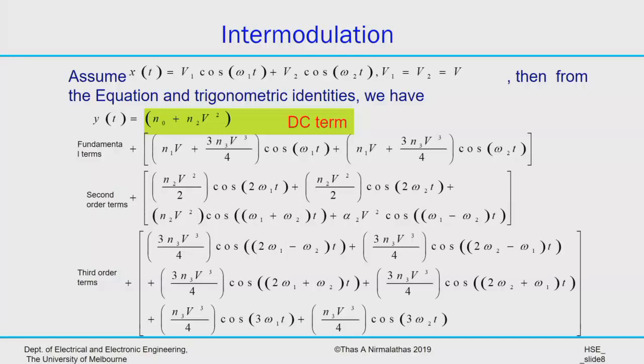And that's exactly what a mixer is. You put in an LO signal, a carrier frequency, and a low frequency signal, and the nonlinearity produces a mixing either up or down. This is down conversion, which means you subtract the frequency from the high frequency. This is up conversion, because you're summing 2 frequencies to generate a higher frequency. So these are the 2 terms often used in mixers. And the second harmonic, we need to try to minimize if possible, otherwise they can cause issues.